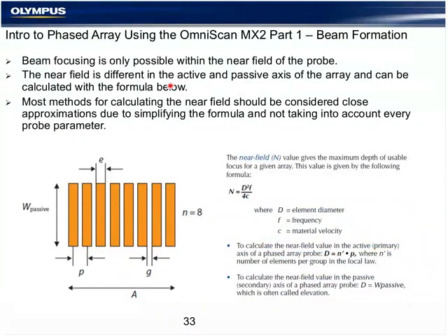So if we were to pull out our calculator, which in phased array we don't necessarily need in our day-to-day business, for any given probe's aperture, the number of elements being used times the size of those elements, and the frequency, you can arrive at the theoretical near field calculation. The near field distance is the maximum distance, theoretically, from which beam convergence or focusing can happen.